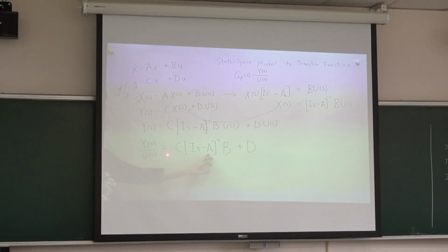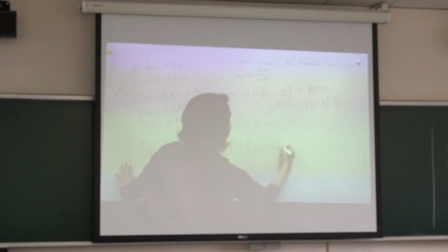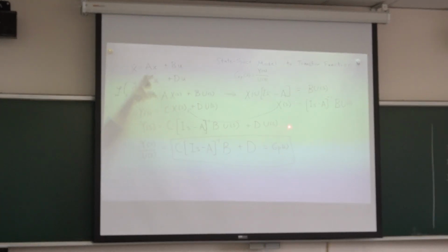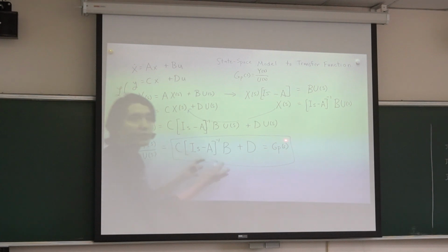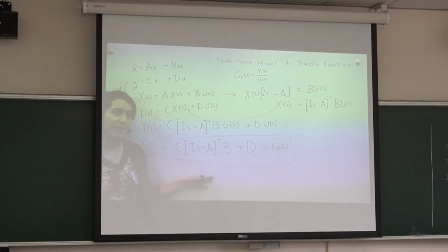So these are all our basic values, and we can use that to find the transfer function. This is the transfer function G of s, and this is our base equation. This is a really important equation for going between the two. You don't have to derive it every time: if you just remember this equation, and you have your system from state space, you can plug all these values in, calculate, and get the transfer function. So we'll do an example with that in a second.